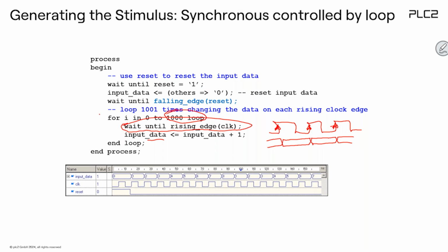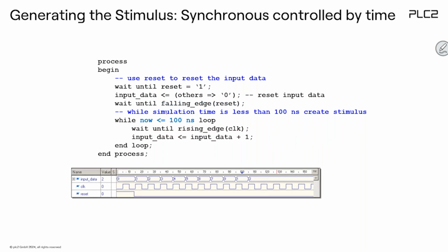A very nice situation for running the simulation here. Or of course, again by time. Instead of having a number of synchronous applied vectors, we just limit this by time. For the time of 100 milliseconds, we have synchronous stimuli, then it stops, and the clock runs anyway, but the value is constant.